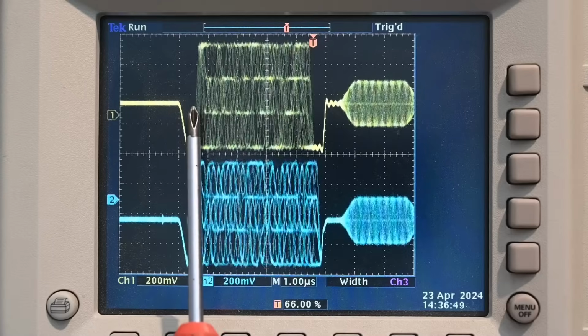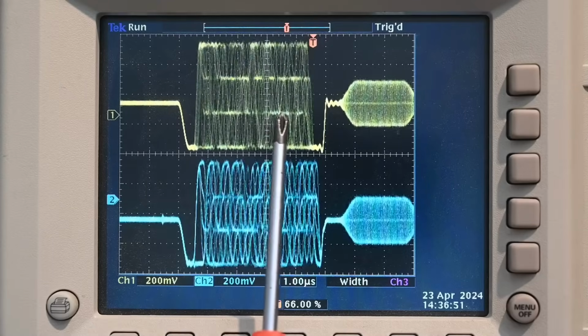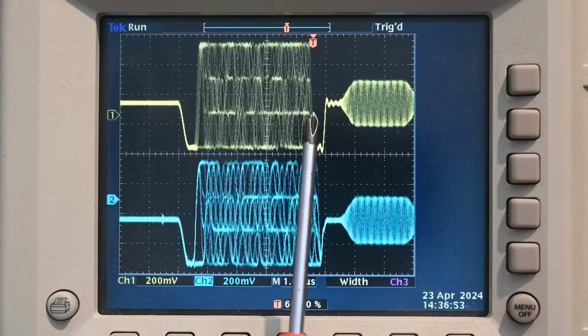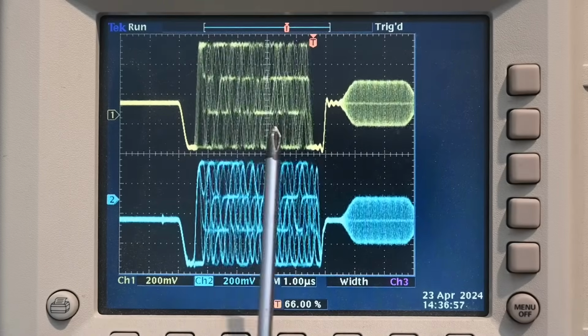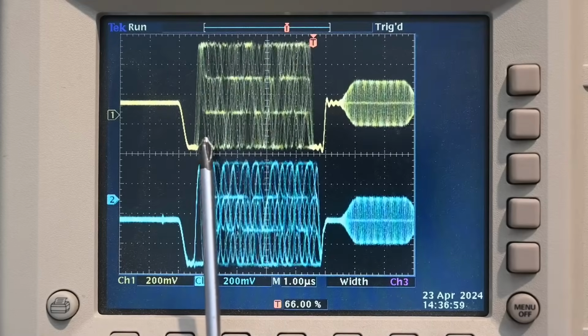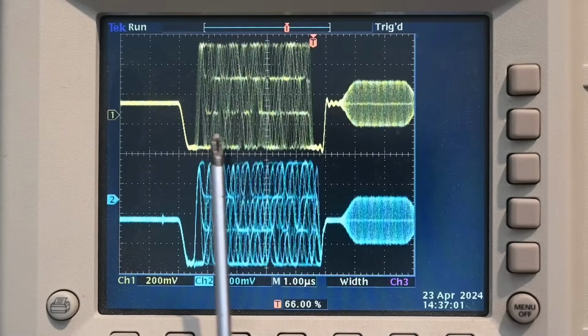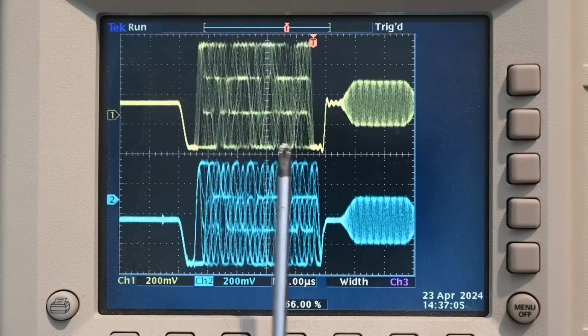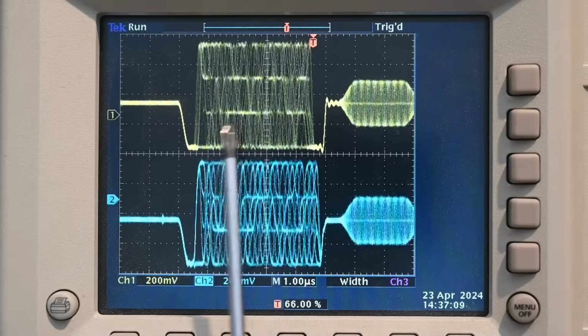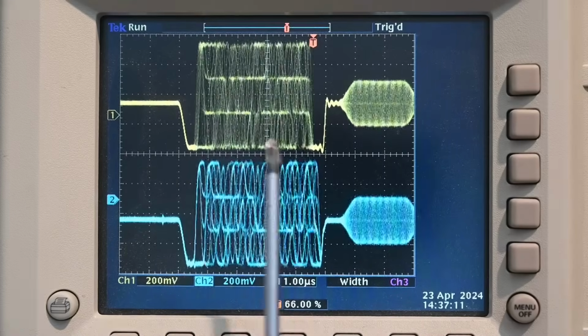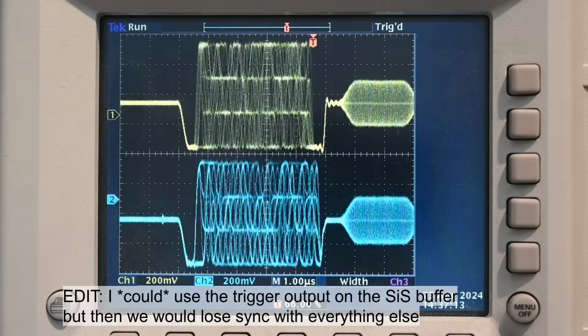When we look at it, it almost looks like gibberish. And it isn't. Because we have the documentation for the system, we know that it actually transmits a variable number of bits. So some lines transmit more bits than others, and that's why it looks quite messy on an oscilloscope. It isn't messy, it's just that we don't have any way to reliably trigger on it.